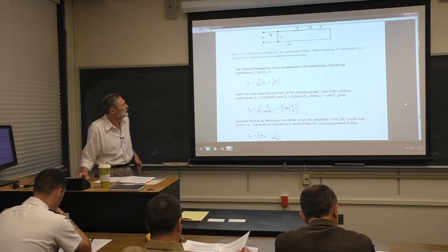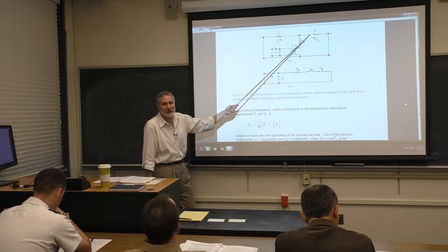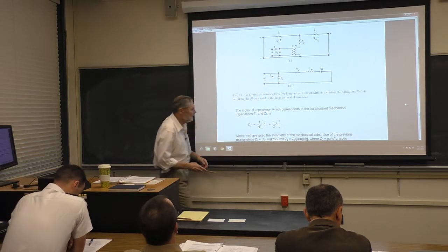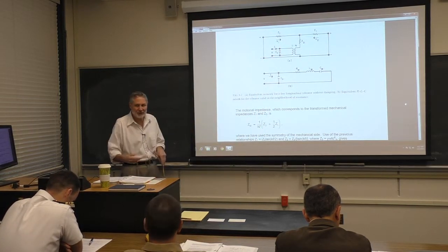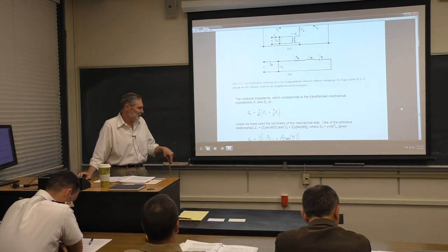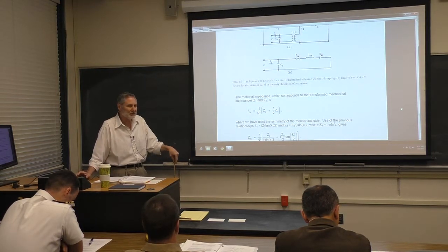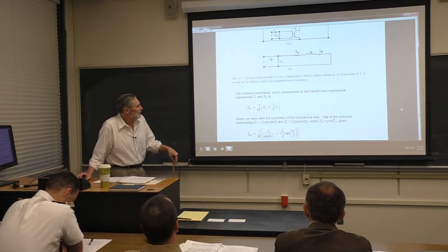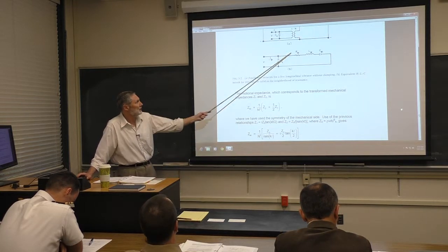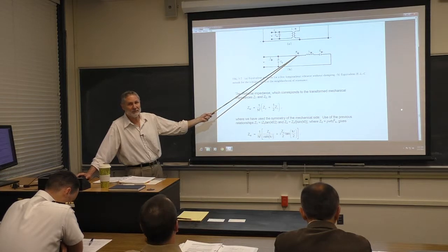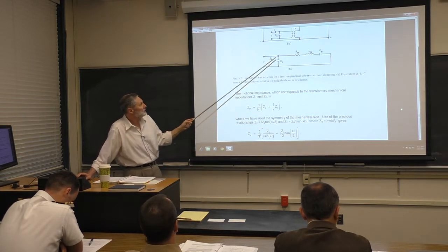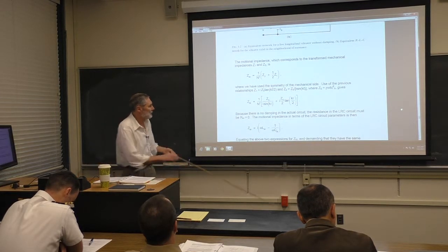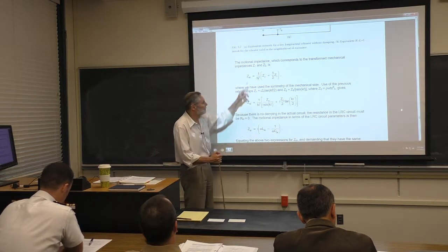Now the first thing to notice here is that there's no damping here. These look like resistors, but these are impedances. Because we don't have any damping in the theory, this makes it easier here. The conclusion here is going to hold with damping, probably as long as it's not too large, is my guess. I don't know. But because there's no damping, evidently the motional resistance here is going to have to be 0. So the motional impedance here is going to have to be just this. It's going to be a reactance. It's going to be that for our simple circuit.